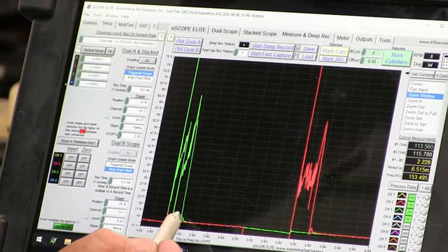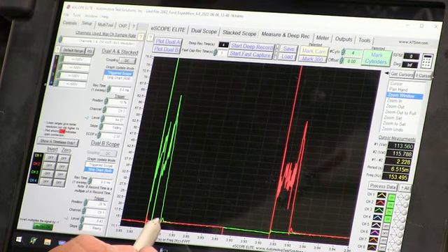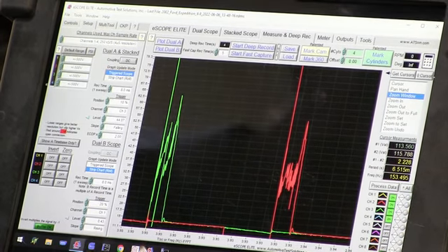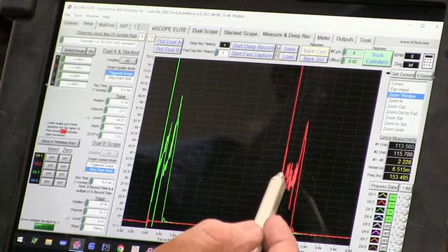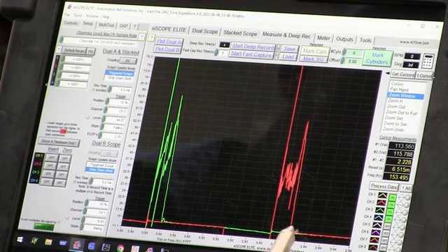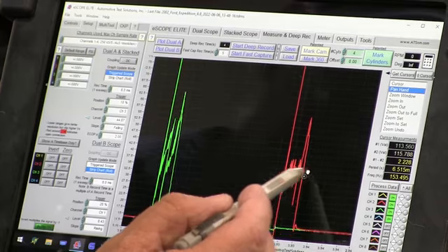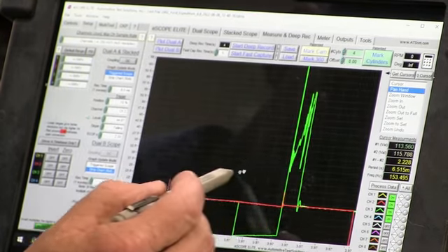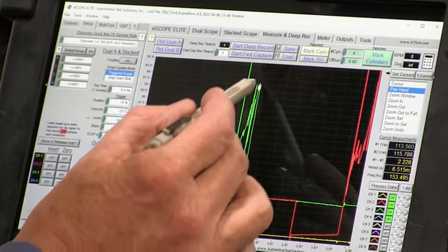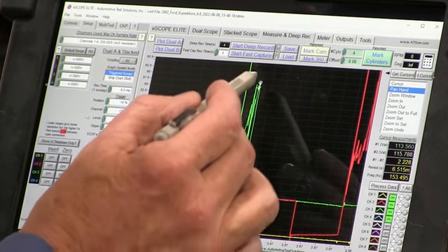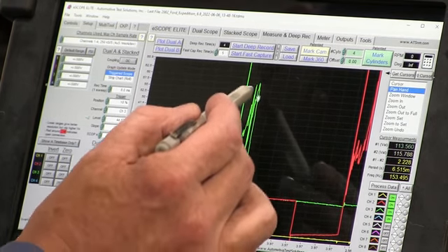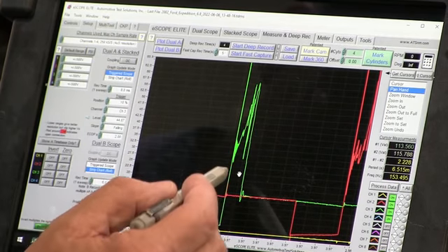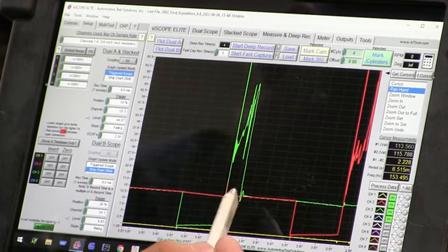Do you see that reserve capacity? The downward slope isn't very big. And again, one has a little bit of leanness. The reserve capacity is okay on that one though. Again, it's a little bit showing lean, but nothing like it was before where it was really lean. That's okay for a snap to look like that, because that was a pretty hard wide open snap.